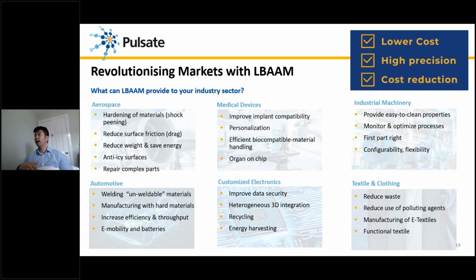And when we touch a bit more on the automotive side of things, a lot of welding applications have been adopted and seen in the automotive sector. Things around dissimilar material welding, thin section welding, or even thick section welding, looking at joining materials that conventionally cannot be joined by other welding methods like TIG and arc. People move on to lasers.